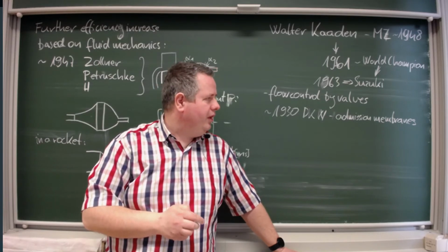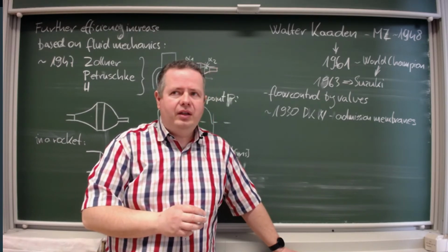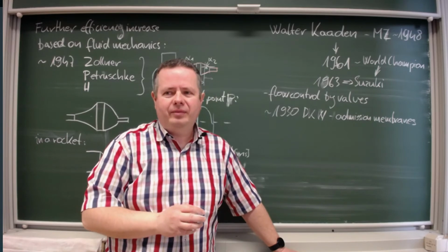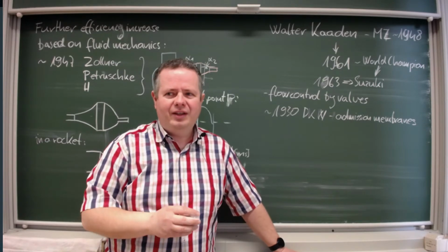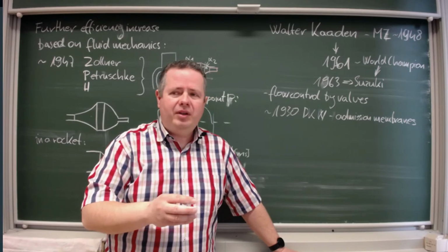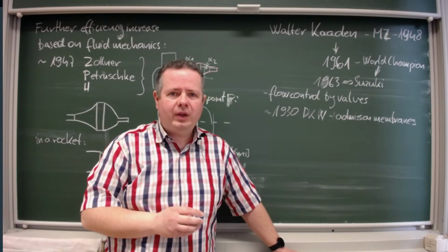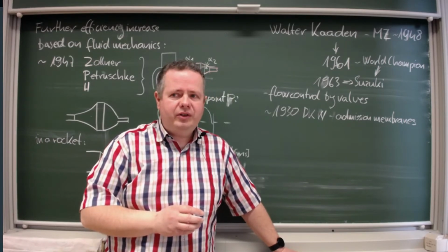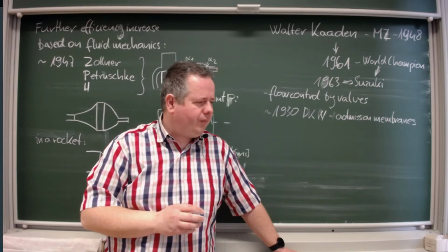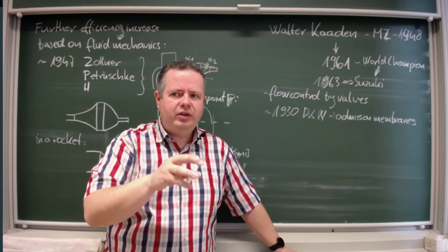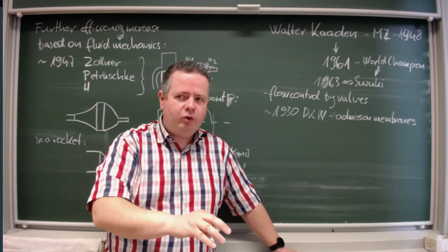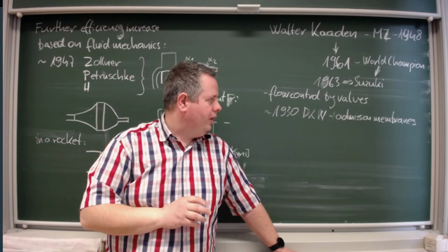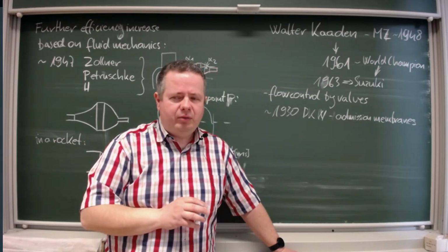When I'm saying it does not last long, I'm talking about tens of hours, or maximum hundreds of hours. So on a test rig it was proved that it's okay, but from a manufacturing point of view, it could not be manufactured cheaply. Though it was used in slow rotating tractor engines, where you don't have high RPM but you need large cross sections to be opened and closed. But for small engines, it was not suitable.